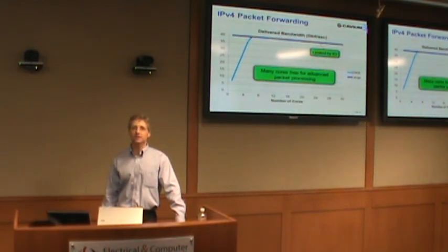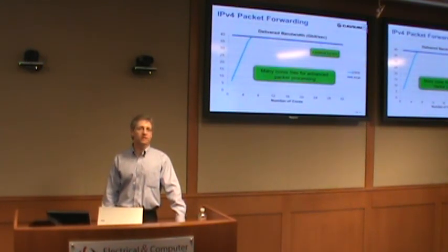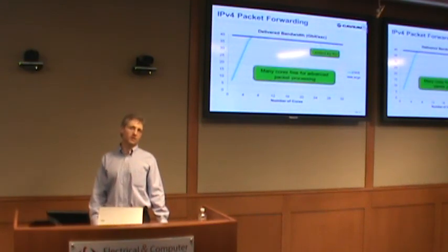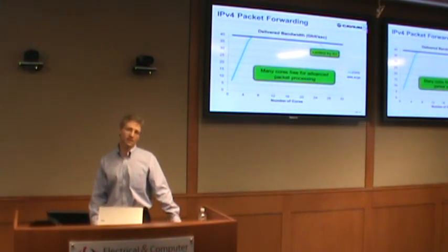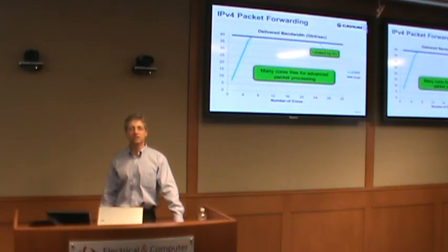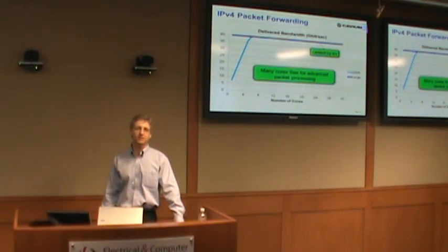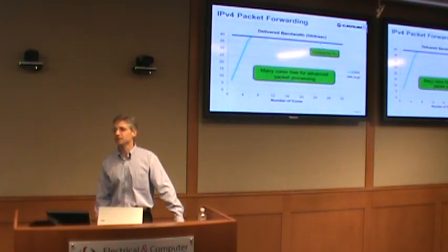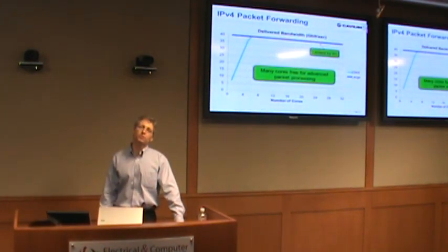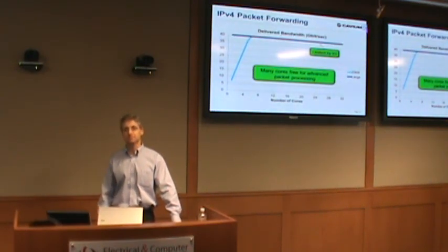The interesting thing here is the I/O limitations of the device are 40 gigabits, and the internal processing for this type of application is much more than needed. You only need about 4 cores. You're up to 4 MIPS cores, and you're up to a 40 gigabit limit of the I/Os of the chip. And you have 28 cores to do other advanced processing, maybe deep packet inspection, maybe whatever.